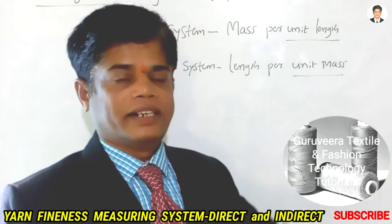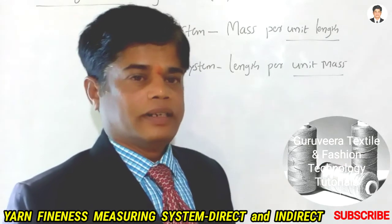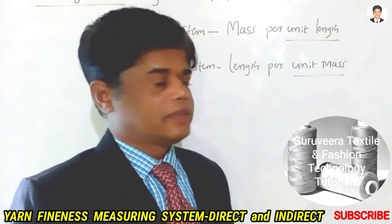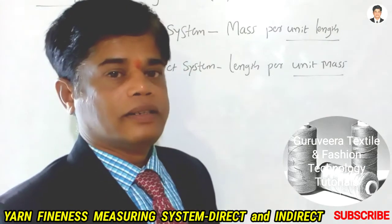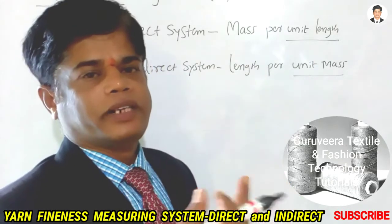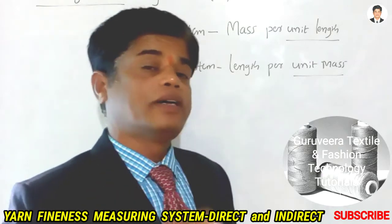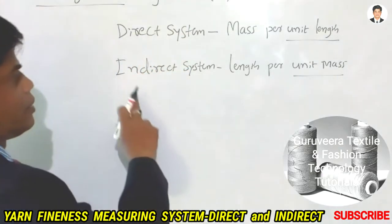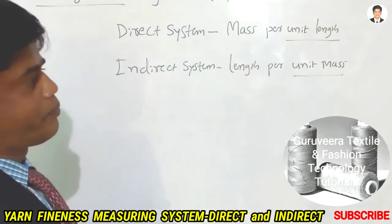These are all measured in denier. There is a continuous filament. But cotton and other materials which are spun, the staple fibers, are spun into yarn. Cut small staples are spun into yarn. Even polyester can be made staple and spun into yarn. That spun yarn is measured in the indirect system.